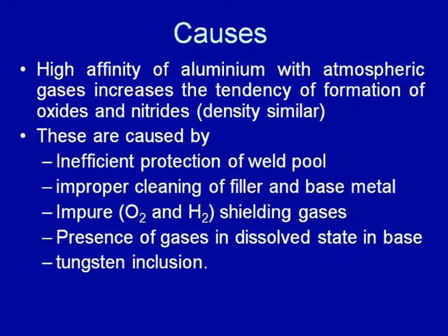Then there is the presence of gases in the dissolved state in the base metal itself, gases like hydrogen or oxygen. If these are already present in the base metal, then these will promote hydrogen induced porosity and aluminum oxide inclusions.